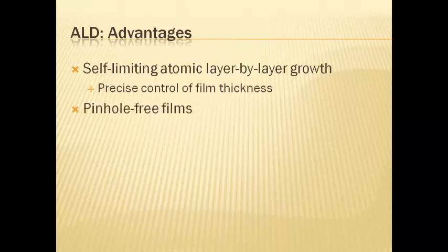Yet another important issue in any deposition technique is the formation of pinholes, which would effectively change the desired electrical property of the device. Pinholes usually arise from localized de-wetting and microbubbles which de-gas during film drying. As is quite evident, such problems are not inherent in ALD because of the unique deposition technique.